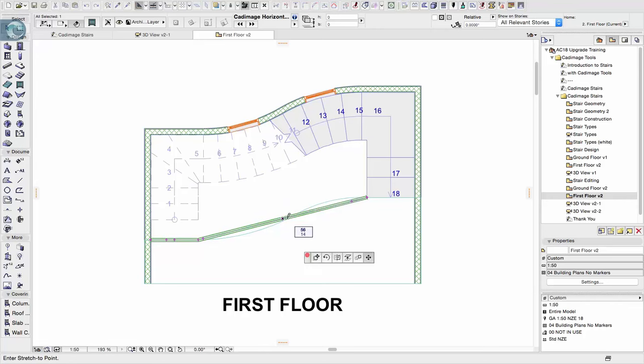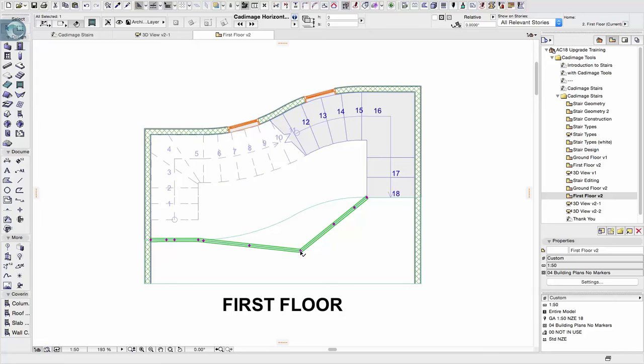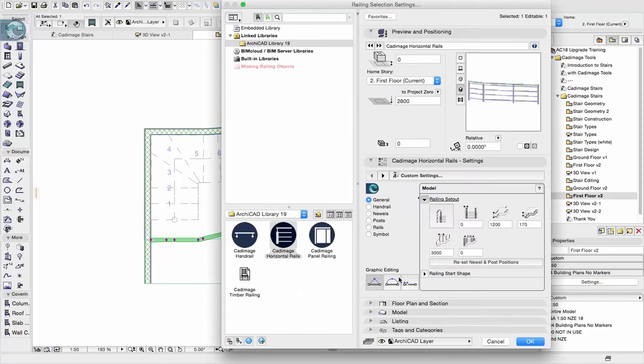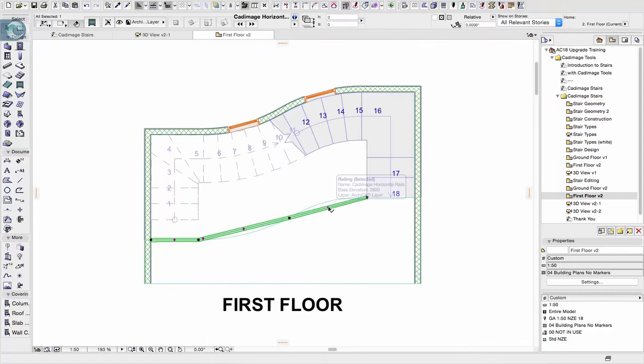We can then move this one, and I've probably just shot myself in the foot. Yep, because I can't see the point underneath. So let's just move that down here completely, and then we'll move it back. So there's a point right there. So it's almost on top of it. So we'll put it there, and that gives me the control points I need to enable me to drop back in, change now to the curving the edges, and then the midpoints that appear allow me to just snap there and there to then create the curve around that slab.